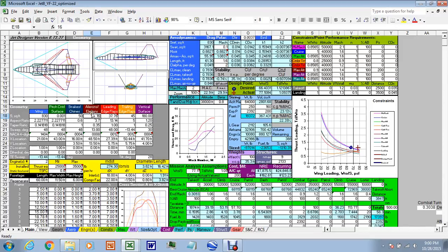ailerons/elevons. And all we have to do to make these ailerons into elevons is put them further from the aircraft's longitudinal center of gravity location. In fact, what we're going to do is put them right on top of the flaps, since we can't use the flaps anyhow, and then we'll control those two things together. It'll just be a single moving control surface. So we do that by just referencing the cell, type an equals there, and click on the cell, and do that all the way down so that we will model the elevons as being exactly the same as the flaps were.